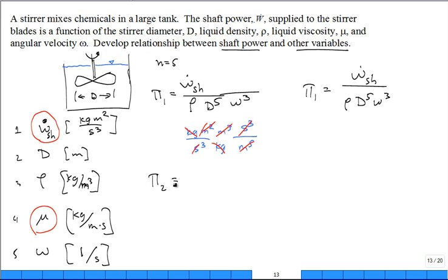What do we start with? Mu. I like to start with probably 1/mu. It may show up like a Reynolds number. Okay, so it's going to be a kilogram divided by meter second, like this, right? Did I get that right for 1/mu? Yeah. Okay. Use rho to get rid of it. We've done this before. So that's a kilogram per meter cubed. Say goodbye to the kilograms.